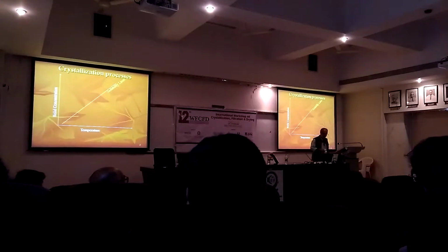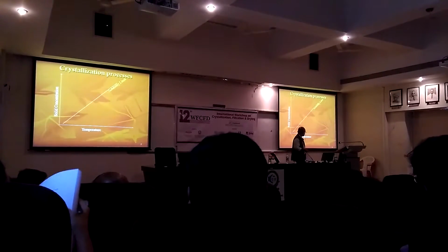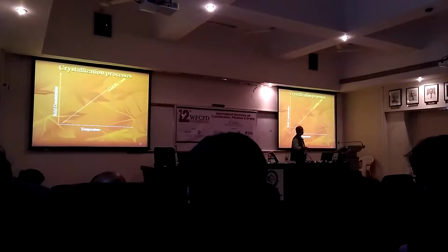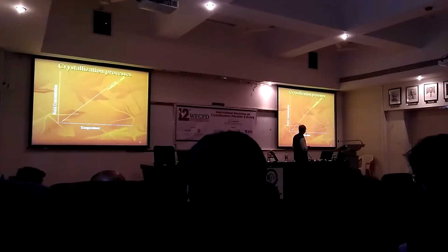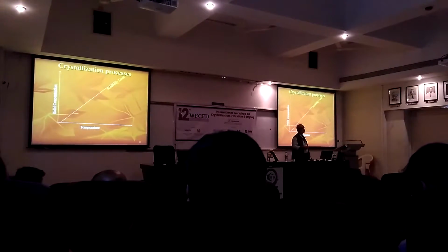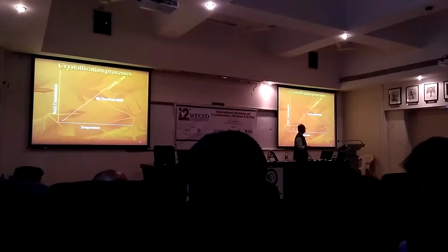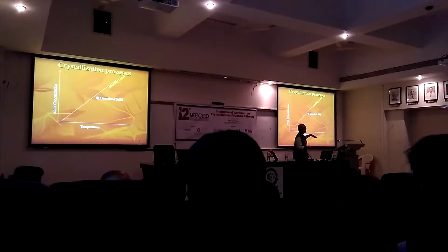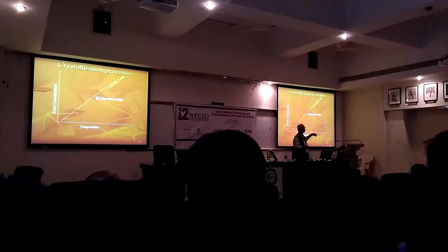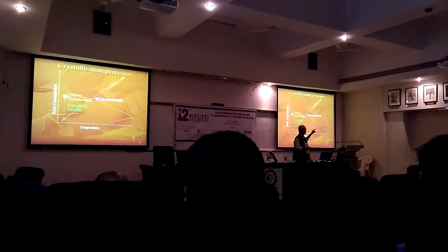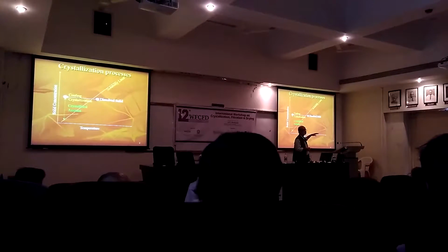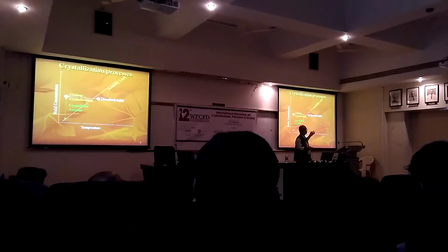Basically, we start again with the same graph. So I have shown it as a linear graph, need not be linear, but this is essentially a solubility curve. And there are two methods in which the crystallization is carried out. First is a cooling crystallizer. So you are on this side, which is unsaturated liquid with solute dissolved in the solvent, and you can cool that particular material, and cooling brings this particular system on the left hand side of the solubility curve.